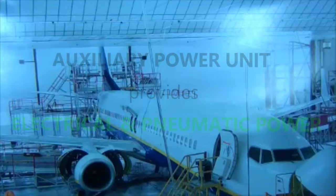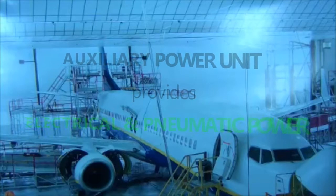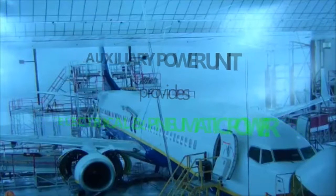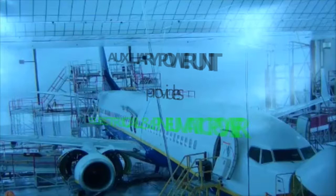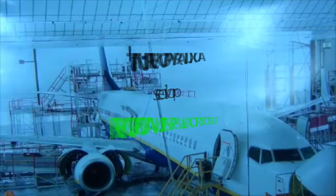Also, I mentioned the air intake flap as an interface with the electronic control box, your ECB. There is this intake flap, and it does open when the APU master switch is selected to the on position. Of course, if you turn it off, then it's going to close that flap, because the flap allows that air to be taken into the APU. So that gives you an idea of the application and the altitude limits regarding the different supply that it has.